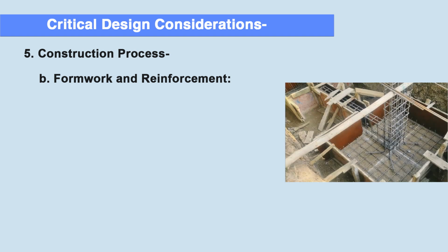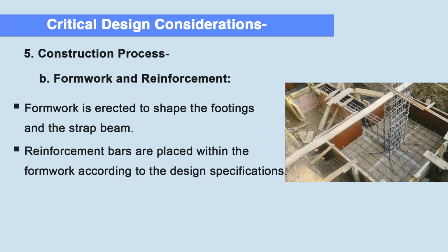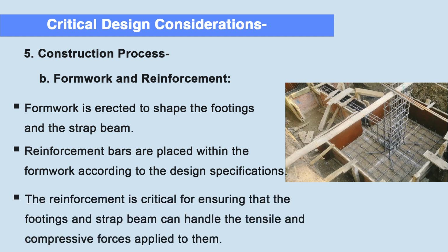Then the next step is formwork and reinforcement. Formwork is erected to shape the footings and the strap beam. Reinforcement bars are placed within the formwork according to the design specifications. The reinforcement is critical for ensuring that the footings and the strap beam can handle the tensile and compressive forces applied to them.